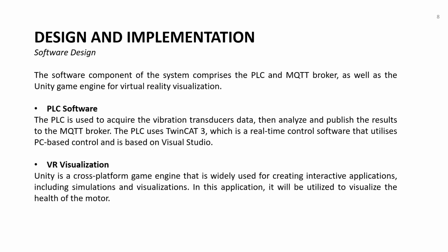And the software design is divided into two parts. So the PLC is employed for acquiring data from the vibration sensor, and it utilizes TwinCat3, which will also analyze the data and then publish the results to an MQTT broker. So the program was developed with structured text programming language and is then deployed on the PLC.